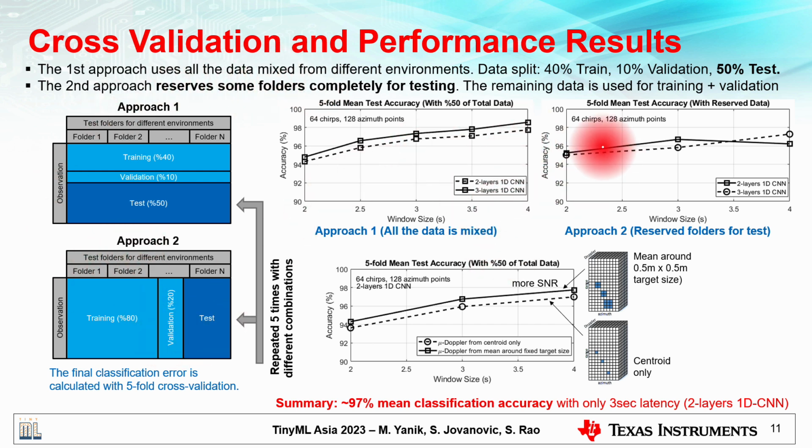One more thing: once you generate the microdoppler, instead of getting this microdoppler information from a single point of the target, if you get it from a certain boundary, then you will get better microdoppler signatures. Think about this, we are not rigid bodies, right? We are walking, and we have different parts of our bodies, like arms and legs. If you accumulate more information from different points, which we did here, you can get much more distinguishable signatures and much better performance metrics.